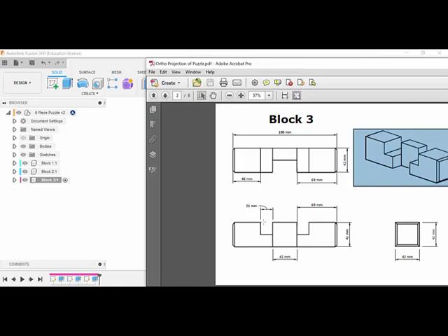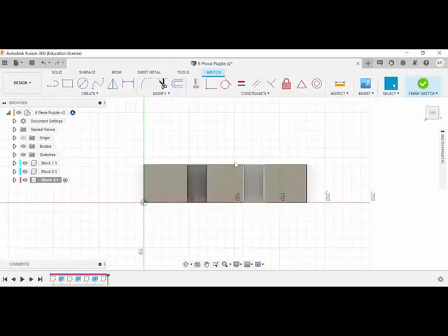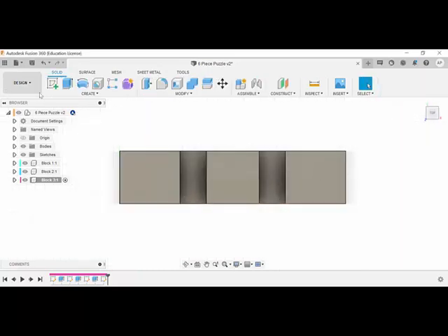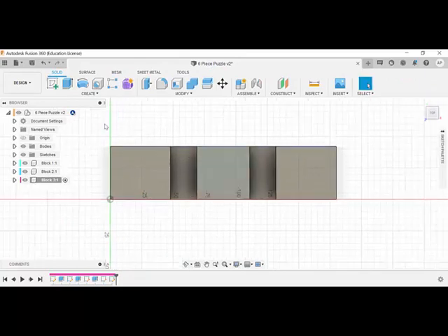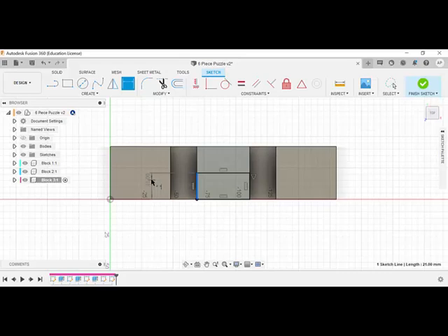And this top view is now a 21 by 42 wide rectangle. So go back to Fusion, and we're going to sketch on the top. There we are. We're going to grab our rectangle tool, and because we already know 48 and 21, and 48 and 21 subtracted from that 180 leaves us with that 42. So make sure when you're selecting this, I'm just going to re-select that face again, get our rectangle going across. There we go. And now our dimension tool, it looks like it went pretty close to the center. It has, it's already 21.